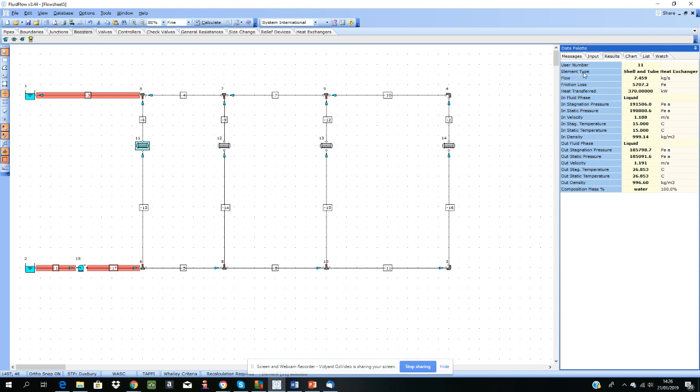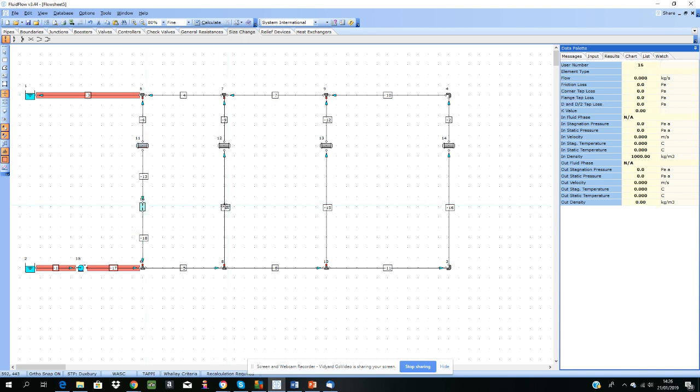Now for this design scenario, the design temperature change across this heat exchanger might be something like 30 degrees C. So we could use Q equals m c delta T and determine what the mass flow rate required should be through each of these branch connections. So let's say we've done that. We can insert now an orifice plate into each of these lines, like so.